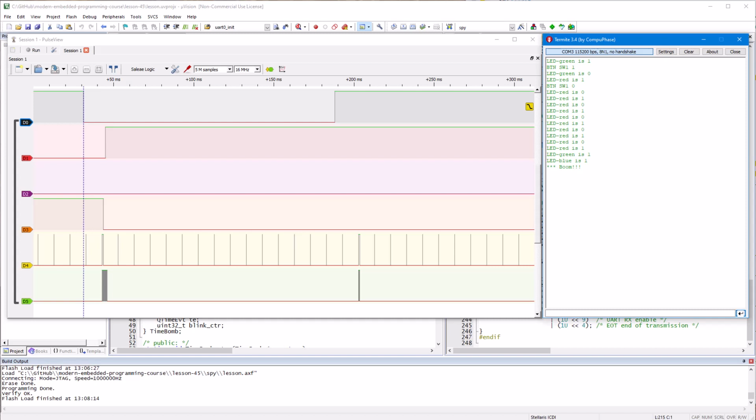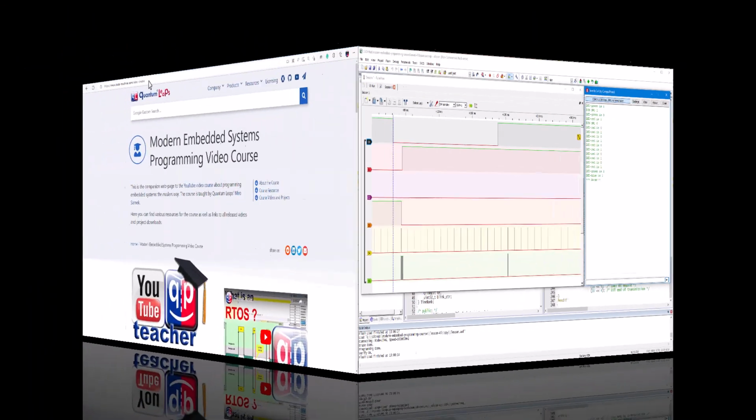The printf formatting to ASCII characters is expensive and produces a lot of bytes, which takes a lot of time to send out. But worst of all is that all that formatting and transmitting clogs the time-critical paths through the code. In the next lesson, you'll see a much smarter software tracing approach, far less intrusive, by orders of magnitude compared to the printf debugging. Stay tuned!